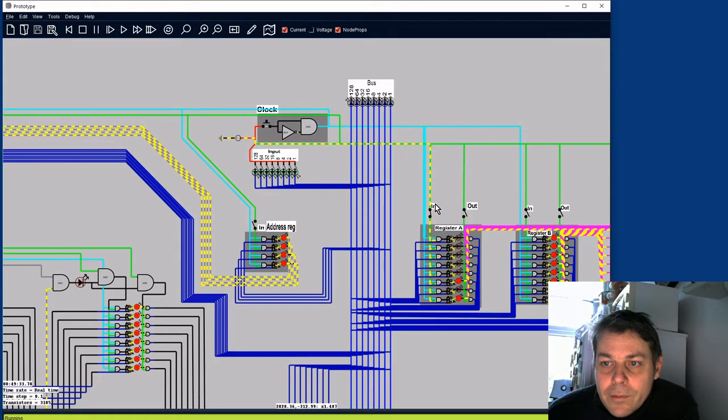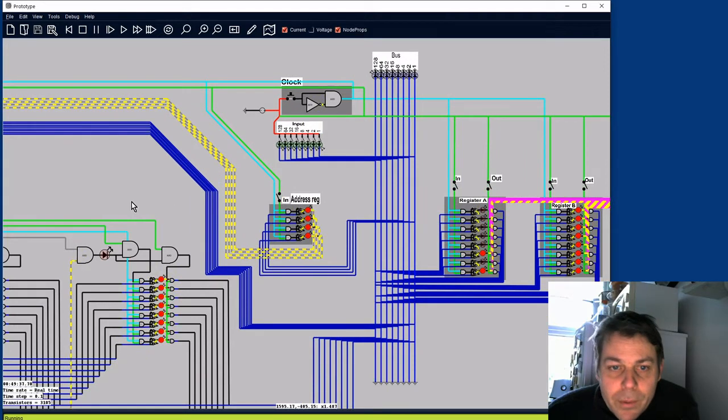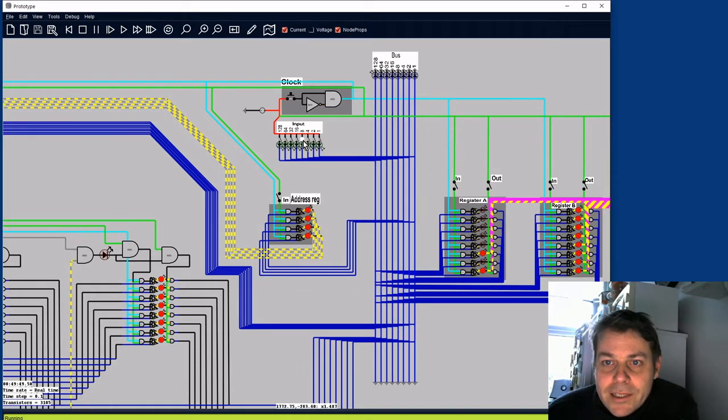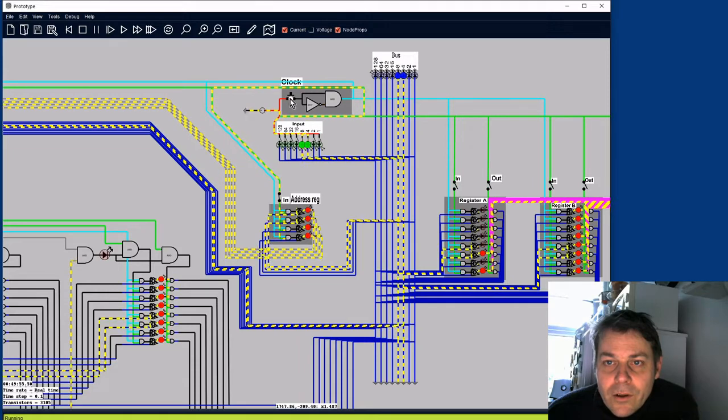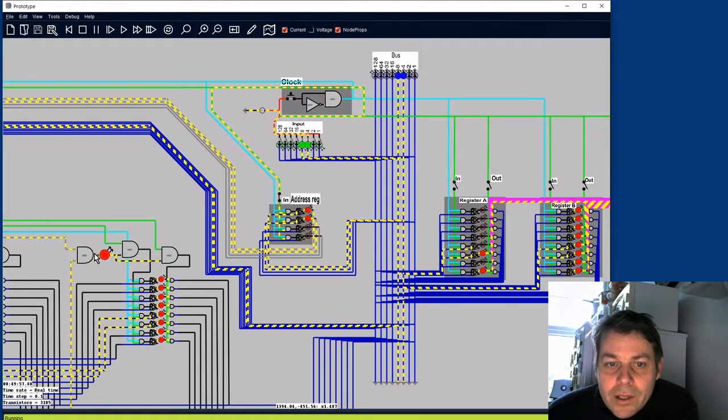We'll switch off the input and the input to register A. We want to move that into memory. If we put it into this cell, say, because it's easiest to see because it's closest to us, the address of this cell is 1100. So we need to load that into the address register. We're only using the 4 least significant bits. So 1100, address register in, send a clock pulse, and we can see that this LED has come on to tell us that we're now addressing this cell.